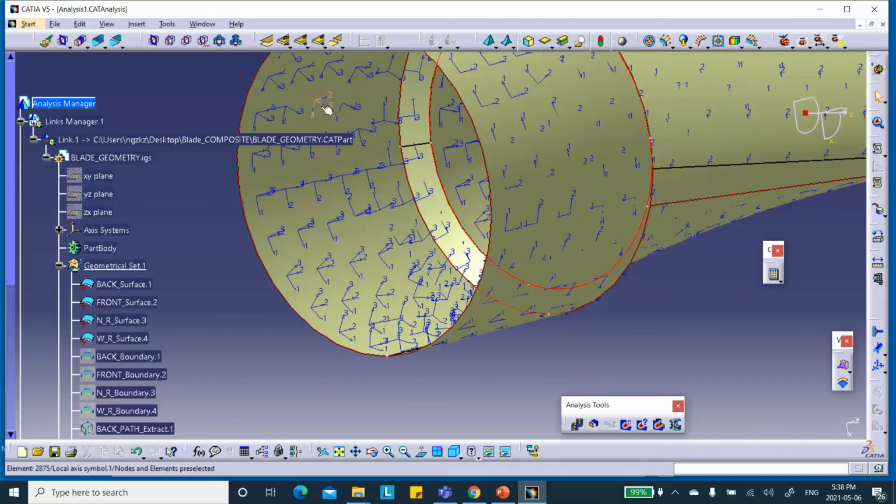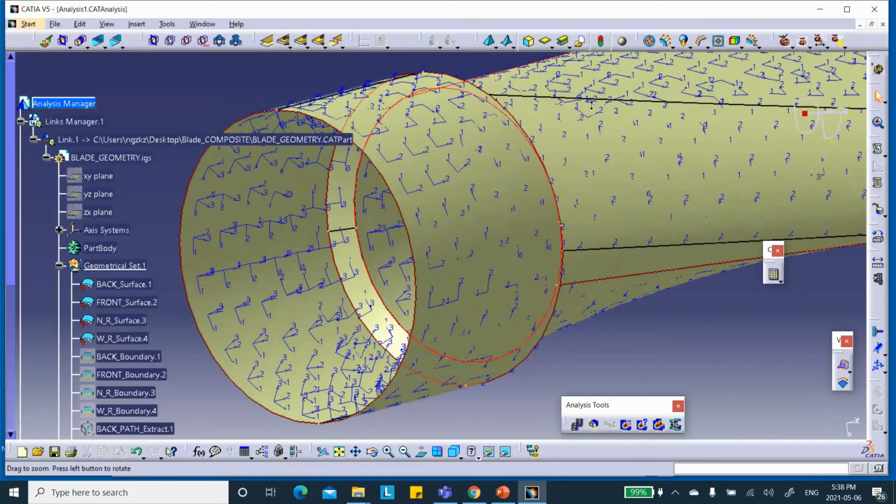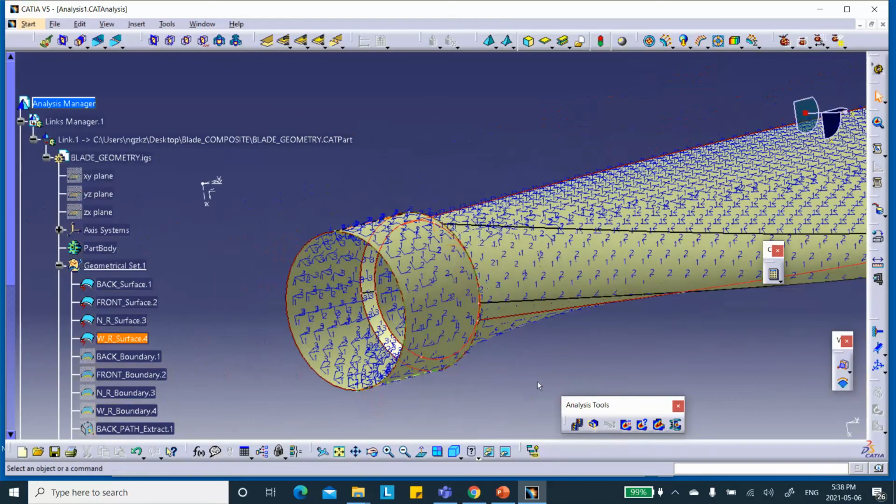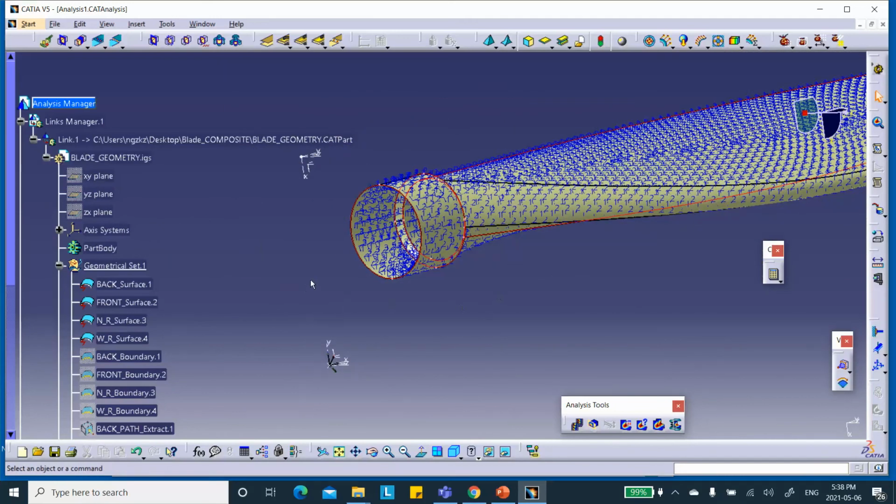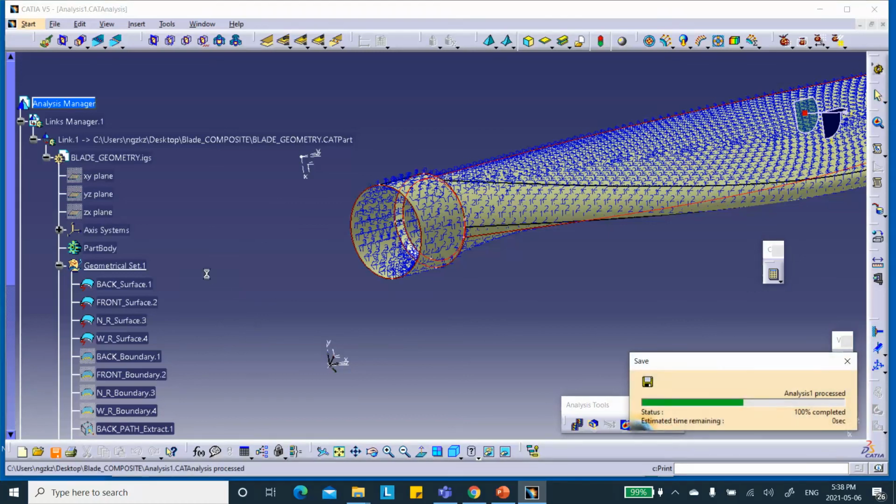If the draping direction and normal direction are in opposite directions, you're going to get results, but the results are not the correct ones. Okay, so these are all okay. We don't have to go and fix the joint. If you watch the previous, I don't know, 30 videos, you see that I always worry about joints. Here I forgot to join, but then I checked and normal direction and the draping direction are the same. So it doesn't matter what the joint direction was. All right. Okay, so save everything. Let me deactivate this plot.